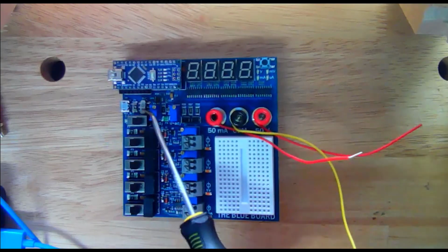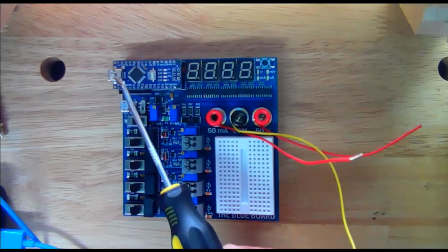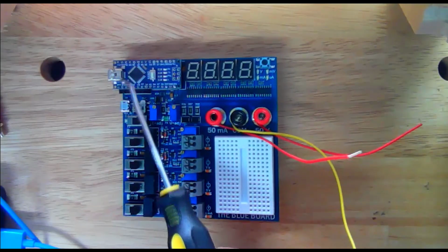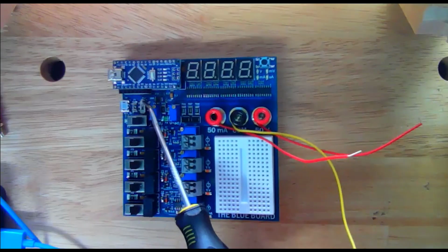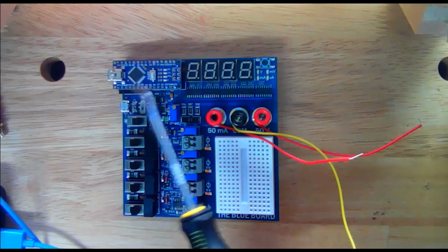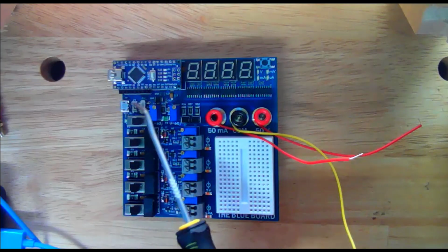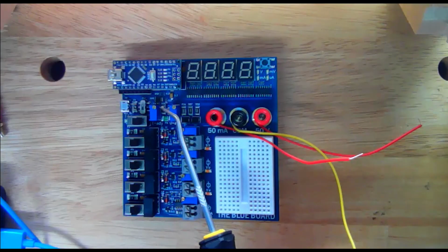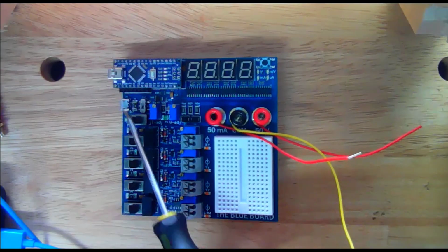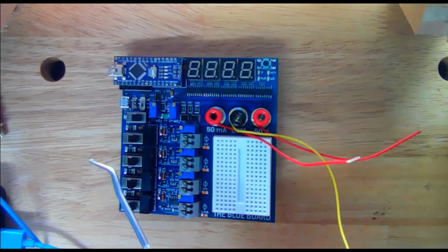You should basically only ever have to have this up, and you really should never connect a USB up to this one. If you do connect a USB to this one and to this one at the same time, this switch has to be in the down position. If it's not, you will break the thing, or you can do some serious damage to the computer you've connected it to. So for the most part, leave this switch in the up position, only power it by this switch here, and you'll be fine.